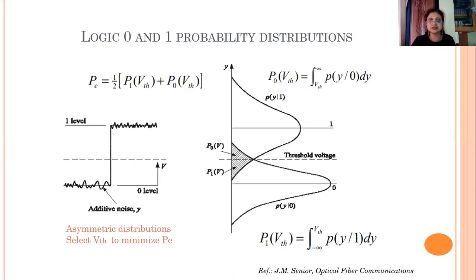And this is the reason, student, that the signal corresponding to bit 1 gets reduced in its amplitude, because here more noise is present because of the presence of light. But here, because of the absence of light, the noise effect is less and hence we get a better signal. I hope you understood the reason for the difference in the probability distribution functions.